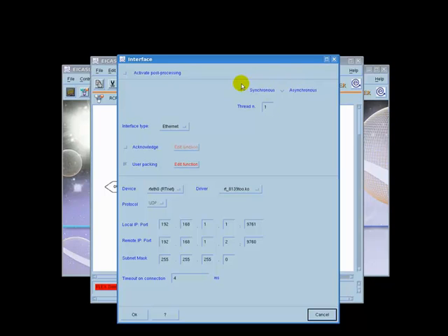2. To set the synchronous or asynchronous mode. In asynchronous mode, the interface runs alone in a single thread and continuously waits for the arriving data. In synchronous mode, instead, the interface can be scheduled with the other functions, and the receiving function is periodically called.